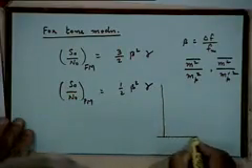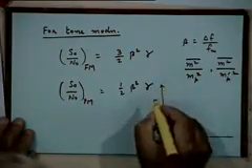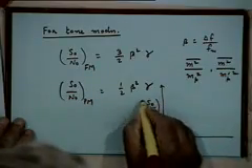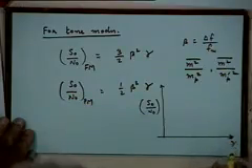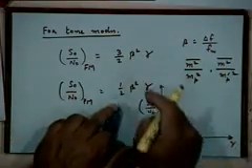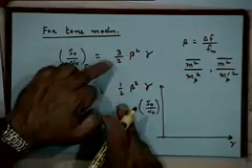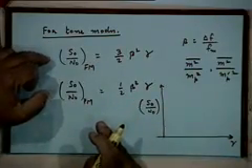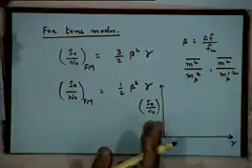The reason I wanted to write these expressions is that it allows me to draw a set of very simple curves for output SNR against gamma. Before I go to that, please note that for tone modulation signals, FM is superior.